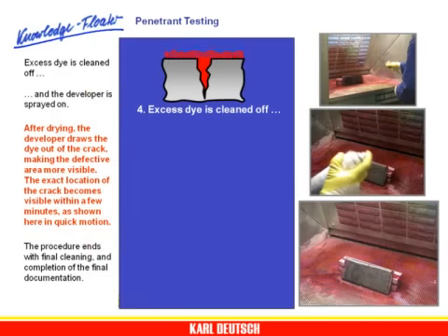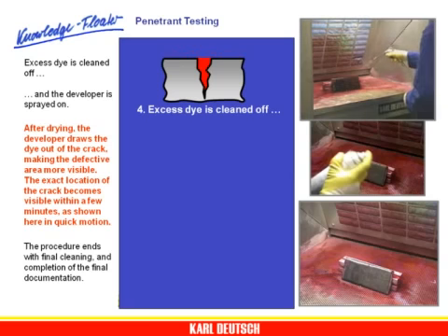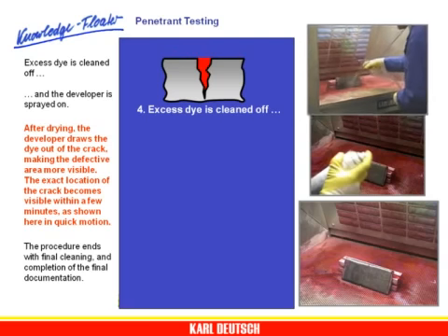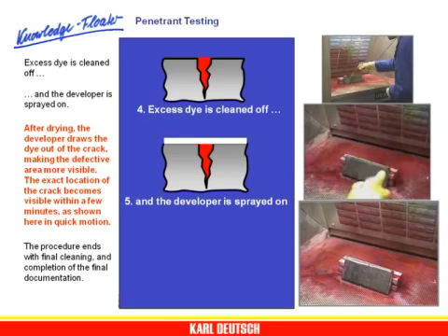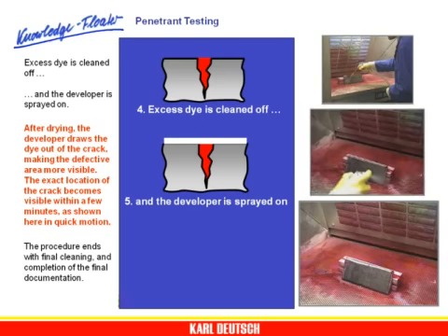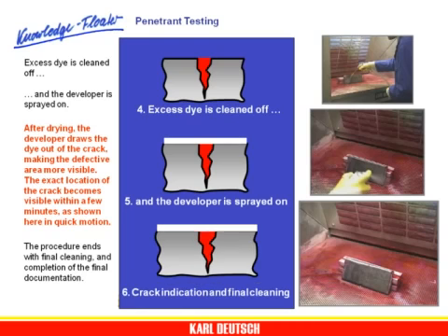Excess dye is cleaned off. And the developer is sprayed on. After drying, the developer draws the dye out of the crack, making the defective area more visible.